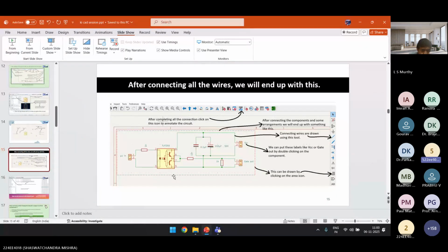For other drivers, sir, if it is a high side driver circuit, you have to use a bootstrap diode and bootstrap capacitor, sir. Yeah, I got your point. But we need the high side driver circuit for the buck converter as the switches are floating. I know, but in this case we are using a TLP 250, right? That is isolated from the input to the output. That can act individually as a high side driver only. So you can use it.